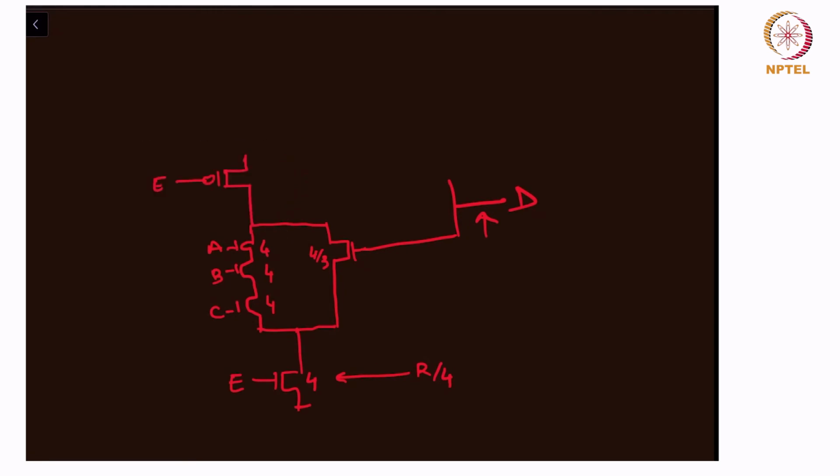So in parallel to E, and it goes to VDD, of course, we have this guy in series. These two are in parallel, so now they'll become in series. So that's D. So I'll just connect that there. That's D. I haven't given the sizes yet because I have to work it out. And therefore these guys are in series, so they become in parallel. So that's A, B, and C.